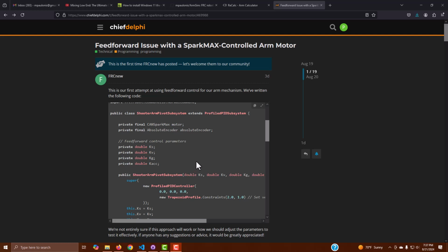One thing that you can do, for something simple like a single jointed arm, is run a simulation and test your code against the simulated arm and turn around really quickly with changes. There's no danger of damaging an actual robot mechanism, so test everything that you want, get it working in simulation. And then when it's done, it's a pretty simple port to get it over to the actual robot.